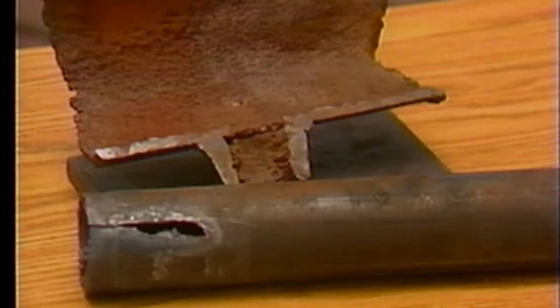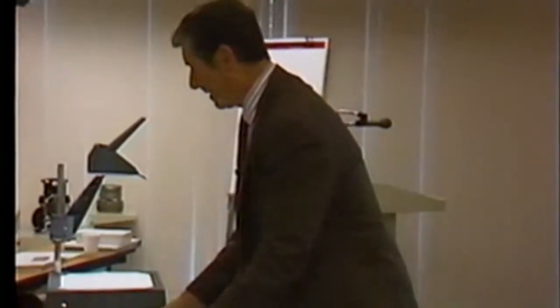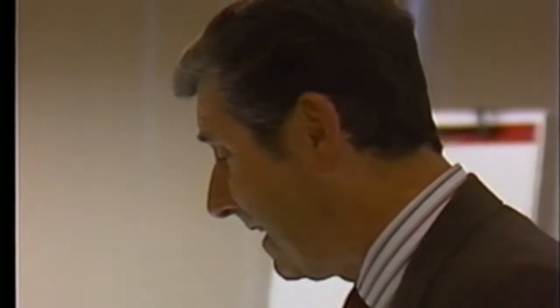So what I'm basically saying here is, if you have air in a vessel, in a piping system and condensing and so forth, these will take place. Can't stop it. So what do you do? You deaerate. First of all, I mentioned that bringing the water to a boil removes the oxygen. It removes a great deal of the oxygen, but not all of it. Because if it was that simple, you wouldn't need deaerators. It says water simply cannot contain dissolved gases at saturation temperature. In other words, you can't put air into water at 212, but it doesn't necessarily mean it's going to come out all by itself either.